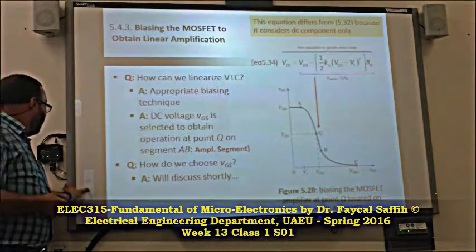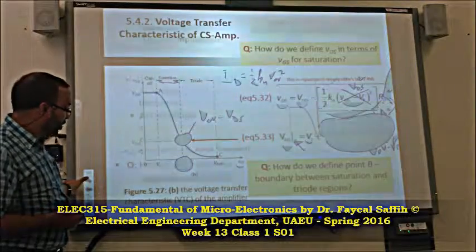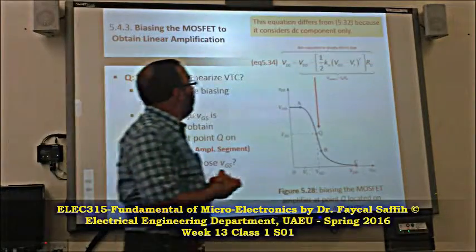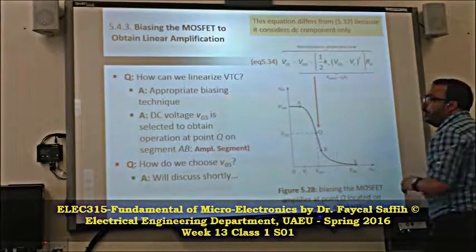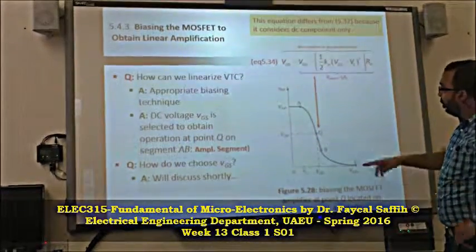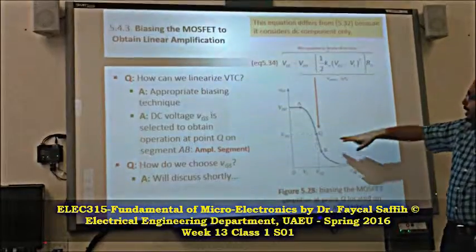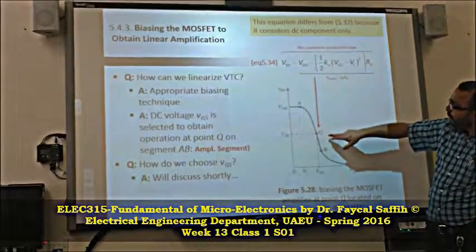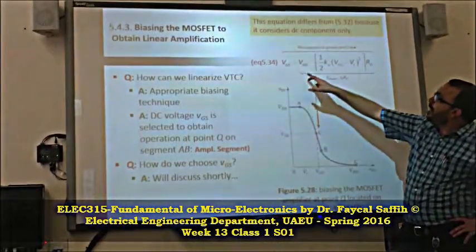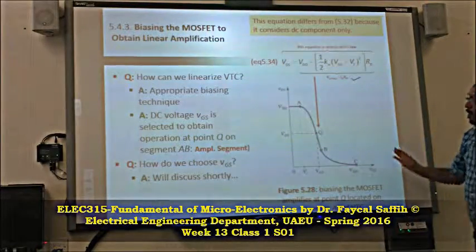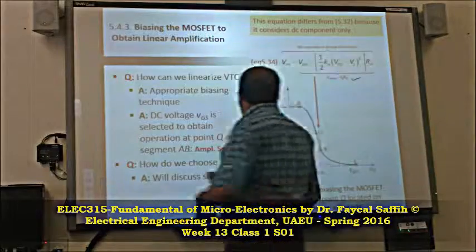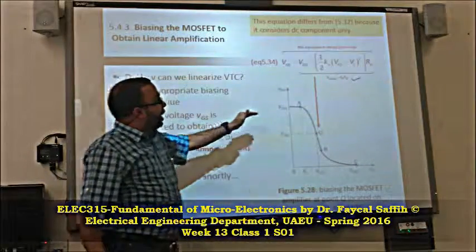Okay, fine. Let's go back. So we solved this, and now we come here. This point is what we call the operating point, Q or quiescent, we'll talk about it later. So the equation here of the output voltage VDS is equal to this, we know that, which is from here. That's it. So the question now is nonlinear behavior there.